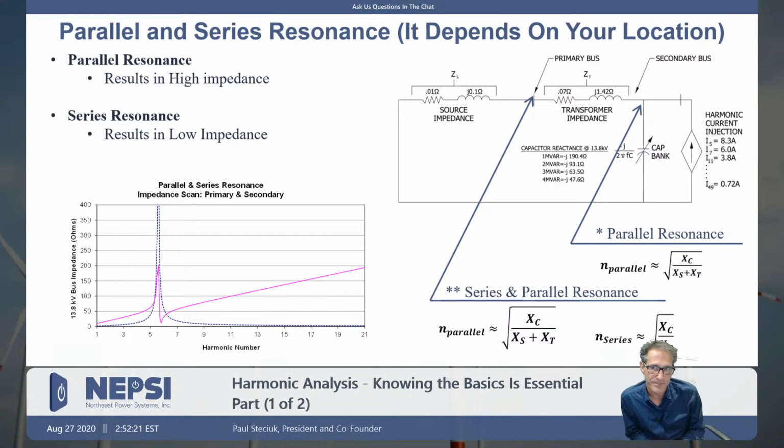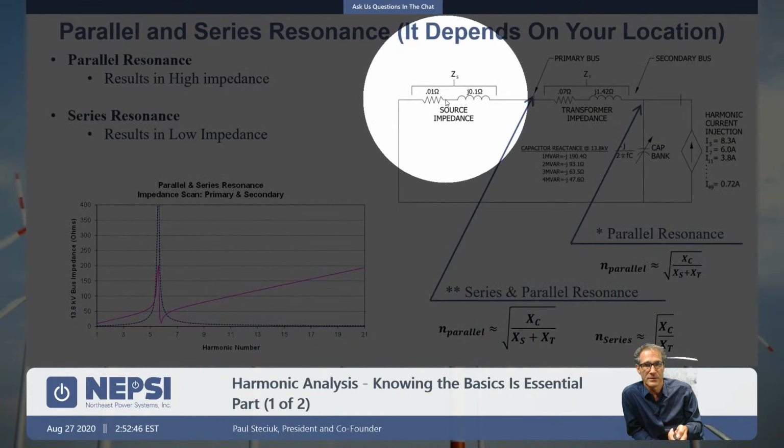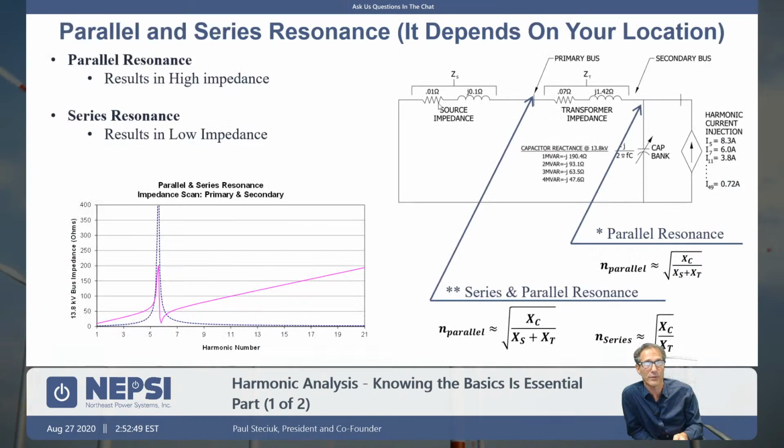First of all, there is capacitance with that transmission grid, and the question is, does it impact the model? When you're doing a harmonic analysis, you have to determine whether modeling the impedance of the source, that transmission grid, as a straight reactance, as I've done here, is adequate, or should I be doing a more complex model? And that really becomes a question: how far back into the transmission grid do you model?